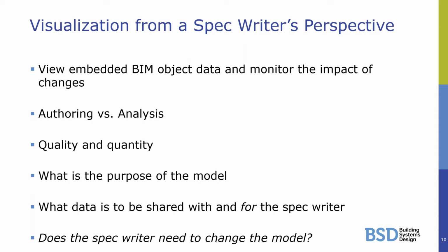Now, with all that, we also think too, if I've got a geometric database, but it sometimes is outside the realm of the workflow of some of our technical staff, in the sense of, well, I'm used to using drawings, 2D representations. Well, why can't you have access to the 3D as well? So another aspect that we've been developing is the ability of the spec writer to reference the graphical data through their own interface. So being able to imbue embedded BIM data and monitor the impact of changes.